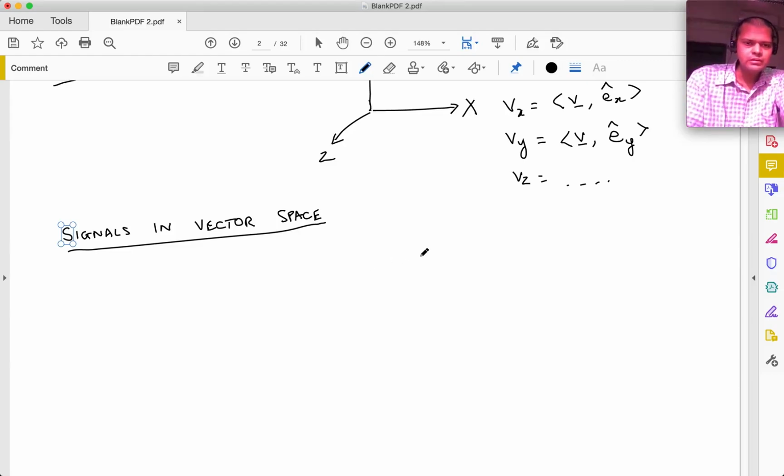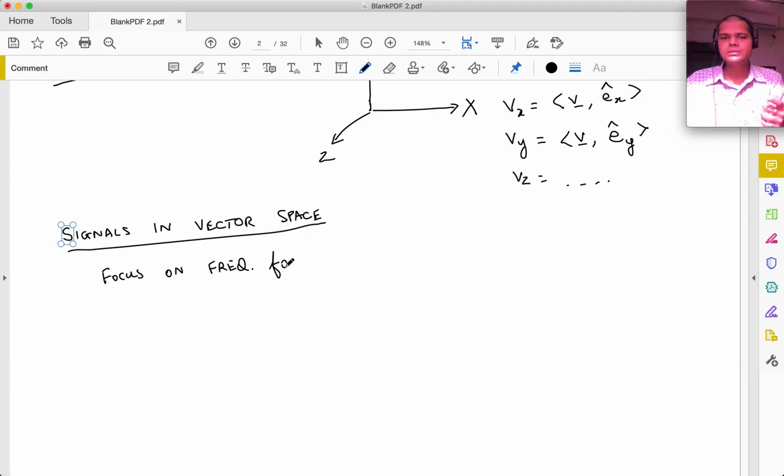So how do we look at this? Suppose I want to look at all frequencies around f0. I want to focus on frequency f0, since we seem to be sending out signals which are only a sinusoid at that frequency, but we change the phase or the amplitude a little bit here and there. So I am going to draw a vector space, let's say a two-dimensional vector space.